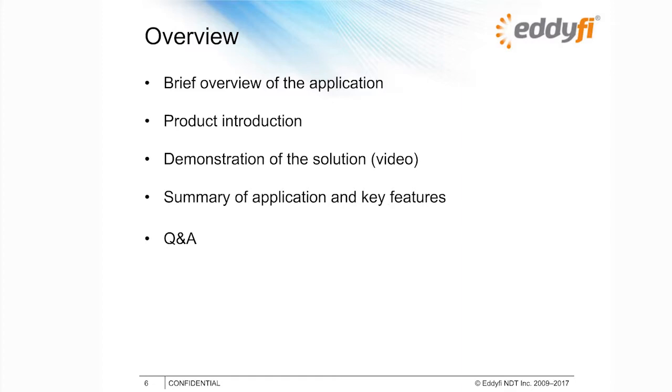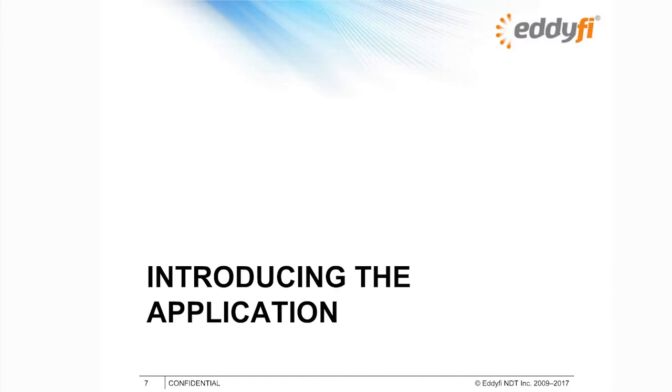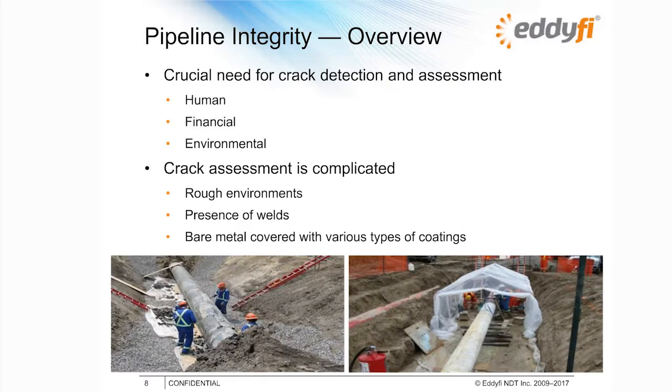So as mentioned just before, we're talking about pipeline integrity and more specifically the in-ditch inspection of pipelines. As you may know, the efficiency and safety of pipelines is very important, as failure can seriously impact humans and the environment, and obviously there's some financial concern if it happens. It's therefore critical to find and assess defects such as fatigue cracking and also stress corrosion cracking, as they can limit the safe use of carbon steel pipelines. Pipeline operators closely monitor their assets and they are very familiar with this type of cracks, which is the most prevalent defect in in-service carbon steel secondly after the corrosion.